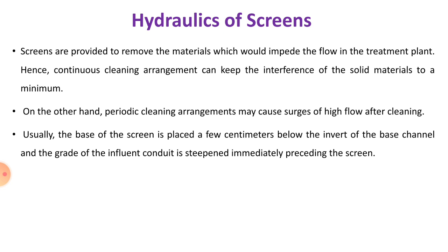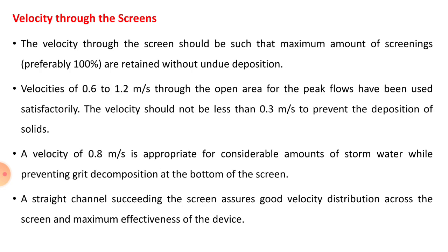So, there will be sudden high currents of the wastewater which may occur. Usually, the base of the screen is placed a few centimeters below the invert of the base channel, and the grade of the influent conduit is steepened immediately preceding the screen.